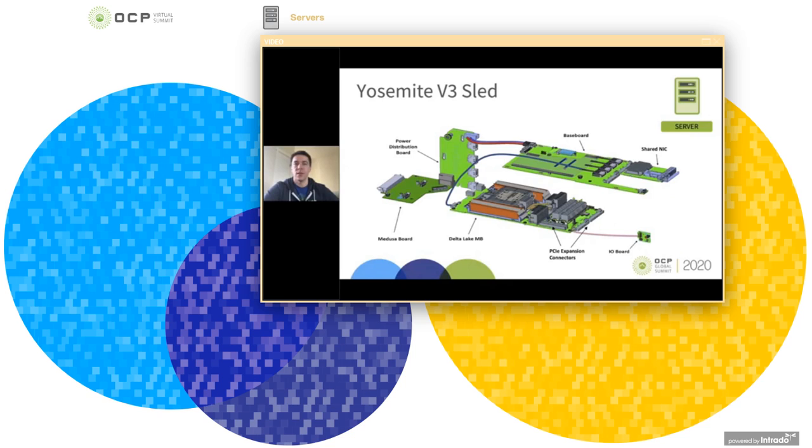On the baseboard side at the top is connected through this PCIe cable, CPU sled management cable that we have, which would basically bring the network PCIe signals as well as the management signals from the Delta Lake or any server card to the baseboard card. The baseboard then is responsible for the BMC management, and it would be the one that would connect through a shared NIC topology when we're doing our standard compute platforms where we have a shared NIC that's supporting 4 hosts underneath it.